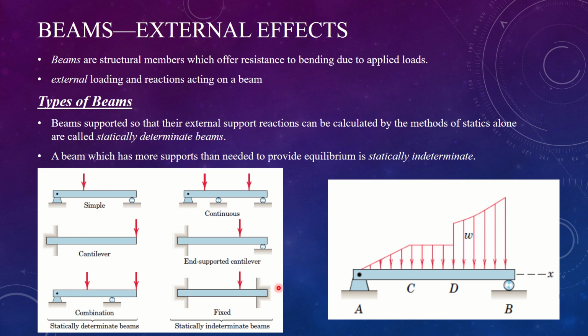Now, statically determined beams are simple beams. When you develop their equations, sum of forces along the x, y, or z axis equals 0, and sum of moments about the x, y, and z axis equals 0. Your number of unknowns and number of equations will be the same. But a statically indeterminate beam usually has more stabilizing structures or supports, or fewer stabilizing supports. This means you will always have a large number of unknowns and fewer equations. In order to understand the two types, let us look at the figure